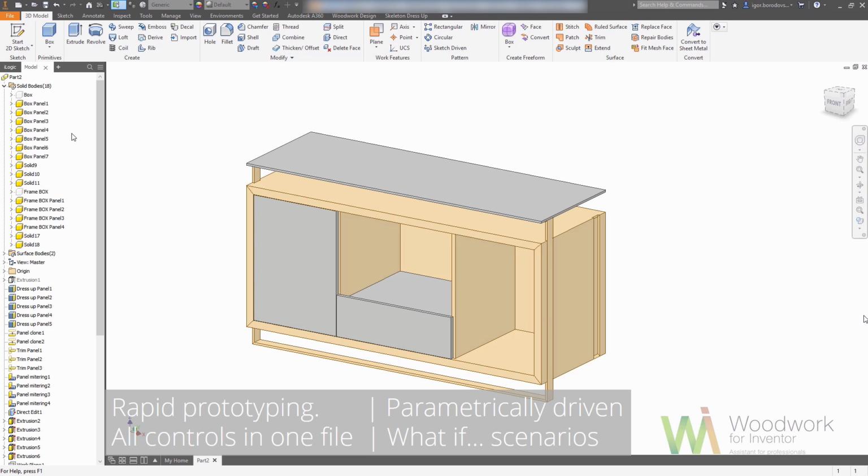So after all, that's the result that we have in the previous step. As you can see, it's a very simplified furniture model, which basically contains one unique item of each of the components. We will have 2 doors, we will have 3 drawers, we will have some shelves and so on, but on the skeleton it's enough to have only one instance of those, because multiplication of those will be made on the assembly. So you can multiply those items in the assembly level like you normally do with Inventor.